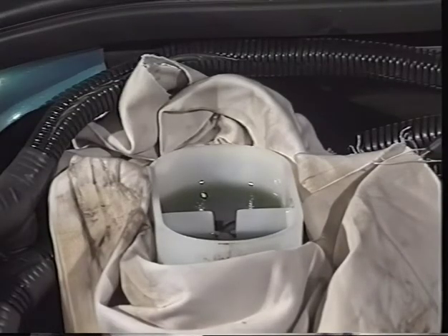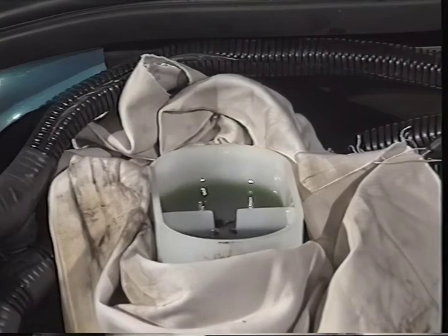Should this valve fail in the open position, all fluid from the large bore will enter the reservoir, causing the brake pedal to be low. This will be easily detectable due to the increased eruption or turbulence visible in the reservoir as the pedal is first depressed.